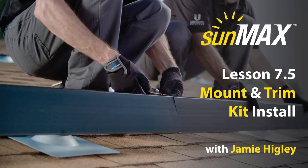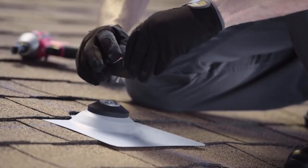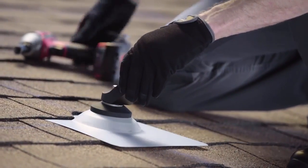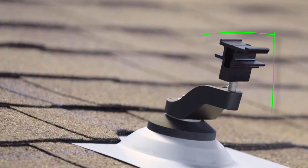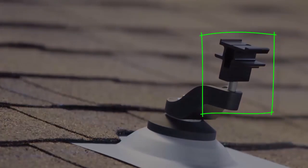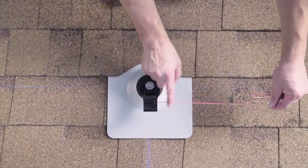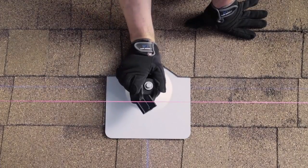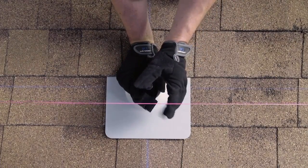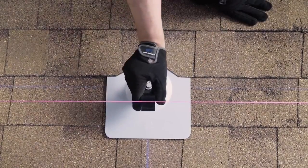Lesson 7.5 Mount and Trim Kit Install. With the flashing installed, begin to insert and install the first row of mounts. At each end of the first row, measure and adjust the mounting assemblies to the same height. The mounting assemblies swivel to increase or decrease the height. Then tie a string at both ends to bring the mounting assemblies to the same height across the entire row. Note that the mounting assemblies for subsequent rows should also be at the same height as you insert them into the frames of modules you are installing.